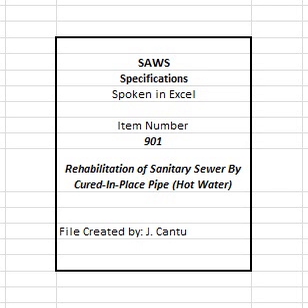901.1 Description. This specification includes requirements to rehabilitate existing sanitary sewers by the installation of a resin-impregnated flexible tube, which is formed to the original conduit. The lining is inserted via an existing manhole or other access and, depending on the system selected, is installed using one of the following insertion methods.